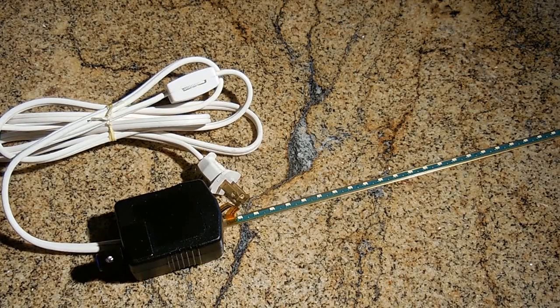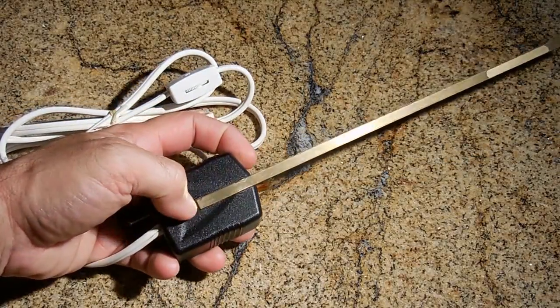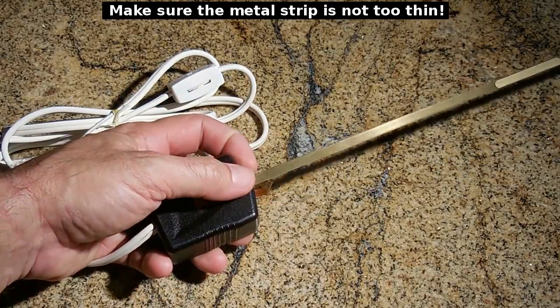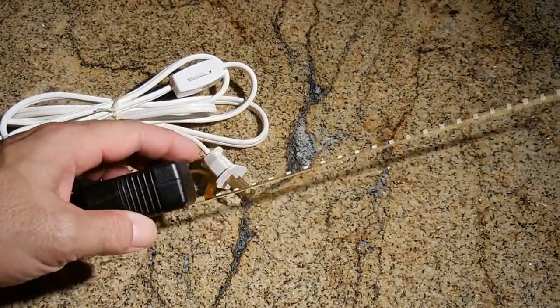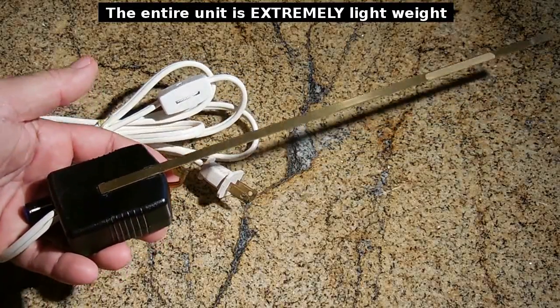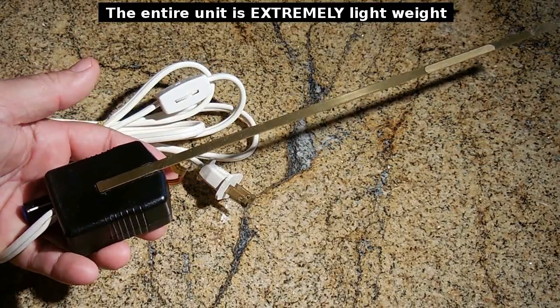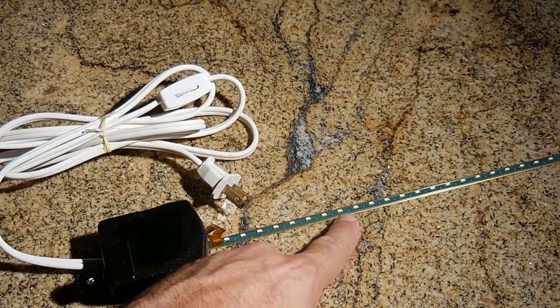That's slightly wider than the LED strip that you see here, and just a little longer. It has to be longer because you're going to have to glue, in my case I use crazy glue, this metal strip onto the back of the box in order to make the whole thing rigid. When I use double stick tape to secure this underneath a counter, everything stays nice, nothing's flopping around, so you definitely want to have a metal strip.